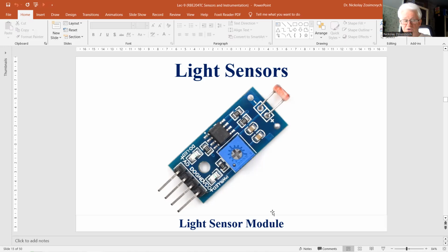Phototransistor, similar to photodiode, somewhat slower. Diode array of photodiodes from a few in a single casing, up to over 4,000 elements on a chip. Line rate up to 100 kilohertz. Gray tone and color. Position sensitive diode, PSD. Radiometric properties as photodiode. One-dimensional or two-dimensional position sensitive.